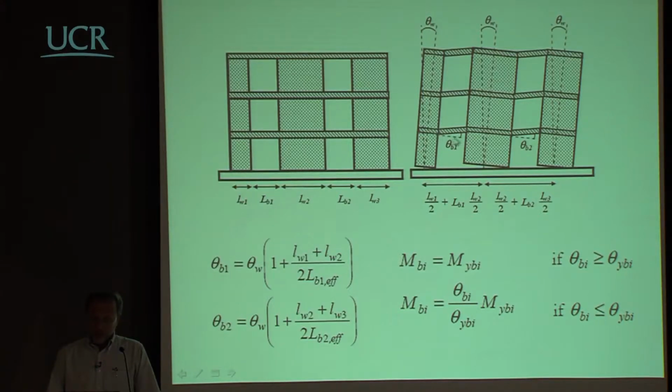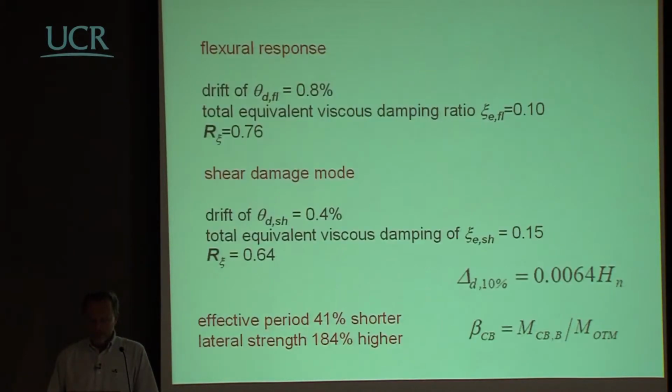Considering, as usual, the effects of the floors here, if the situation is that you have just the floor, which is the simplest situation, you know what the bending moment will be here and here, provided that they will be controlling, or what they will be if they will not be controlling, because the rotation capacity will be the one given by the walls and not the one given by the floors.